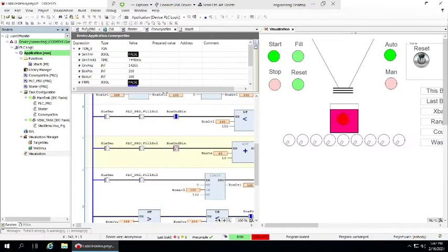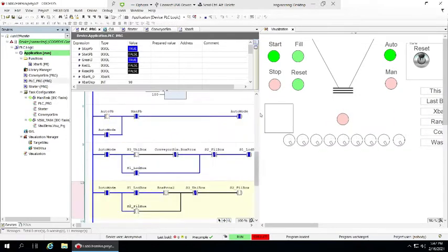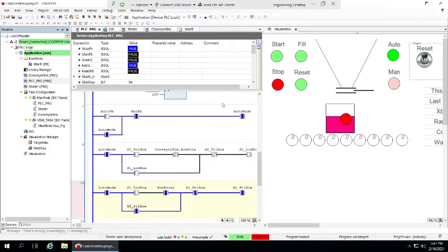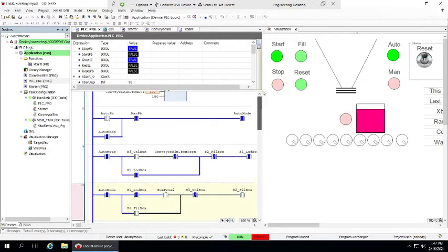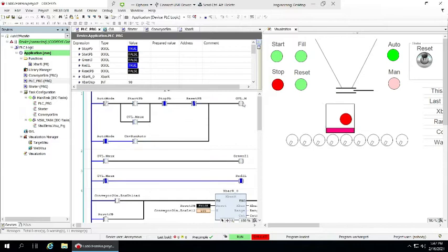And so here's the PLC program that's operating this system. So I have a PLC program, and I have some other stuff in here that's just simulation. But let's see what we got. So I'm in auto mode, and I get conveyor run. Then I'm going to pick up the motor starter, and the motor starter, then the auxiliary contact comes back and picks up the green light and the red light. And so when it stops, you can see the red light turns on. There it goes. When it starts again, the green light comes back on.